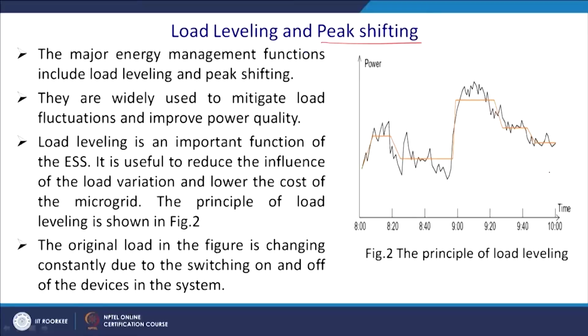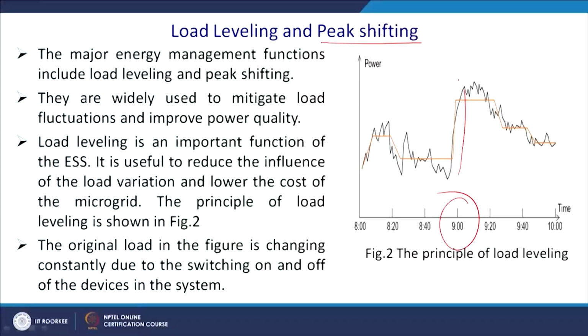You can see that, and we may capture the data in the morning. You start your activity from 8 am and thus your load increases, and then again it will come down maybe for a short interval of time, and at 9 all of a sudden your office starts and you switch on the ACs and all those things, your peak load will suddenly jump by 20% or 30%, and it will continue so. Then gradually again it will come down and settle down to this load.